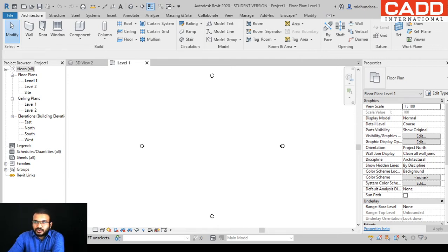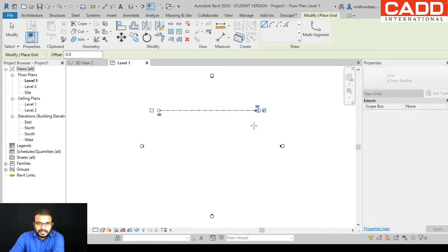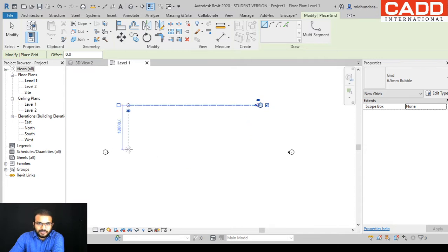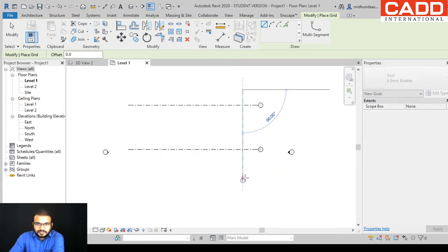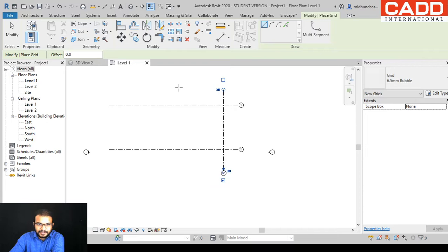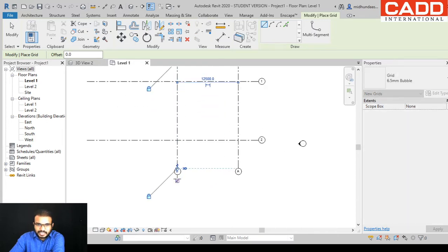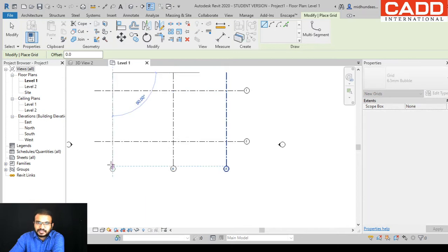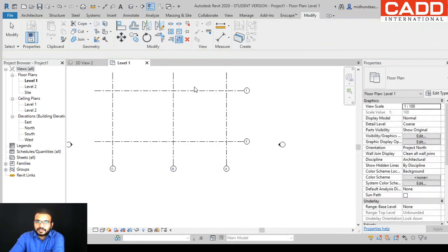Okay, so from this situation what we need to understand is that we will be creating a typical Revit structure as per our previous system, as per the topics we discussed last time. Here I'm simply drawing a grid like this, both horizontally and vertically, and renaming them. Hope you remember the purpose of the grid; we already discussed it last time. It is a datum element to place our building elements, especially the walls.